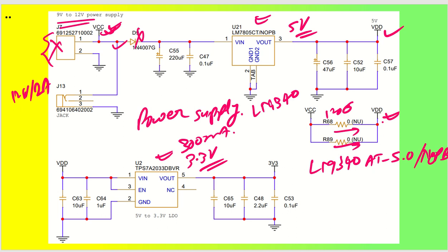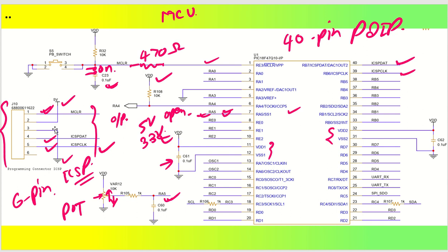We are ready with our reset switch, our programming connector, and a small ADC connector. We are also ready with our bypass capacitors on the power supply. This is the minimum requirement that we needed. You don't have to connect OSC1 and OSC2, the external oscillator, because this microcontroller has the capability of an internal oscillator as well. So you can utilize it, or you can still mount your external resonator.